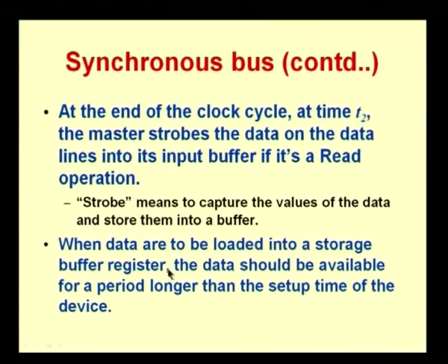So, when data is to be loaded into a storage buffer register, the data should be available for a period which is longer than the setup time of the device. Since I have to store it into the buffer, remember whenever we store into any buffer, which is essentially any memory component, there is something called a setup time and a hold time. So you need to make data available before the setup time, and you need to hold the data for a little time which is more than the hold time. Okay. So both these have to be taken into account when you are deciding on the clock pulse width.